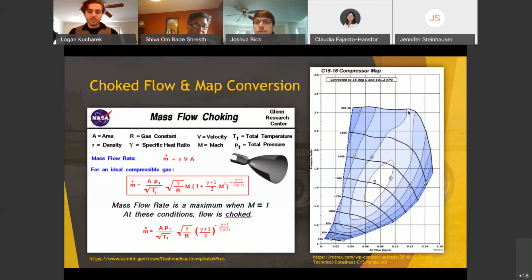Assuming 100% volumetric efficiency, choked flow would happen around 11,000 RPM. This is verified by choked flow calculations the team has done previously, as well as conversations had with members of other Formula SAE teams who run the same engine that we use.